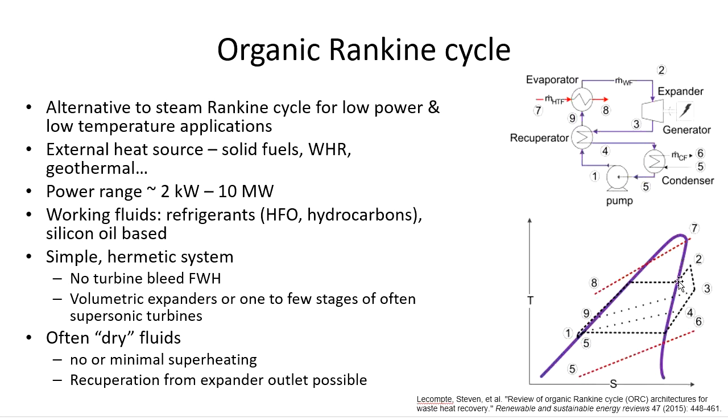That means if you would have expansion taking place directly from the saturated vapor, you would not go into the wet steam, as would be the case for the water, but you are moving into more and more superheated vapor, further right from the saturated vapor curve. So the superheat might be really small, just for technical purposes to limit droplets entering the expander, so that the expander would not be harmed. Then the expansion takes place to the low pressure isobar.